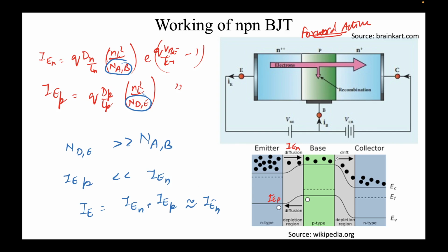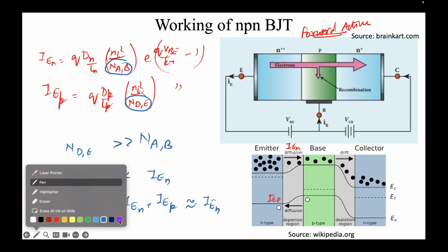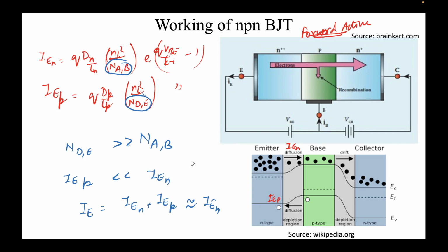And in all this analysis, what we had ignored, I should bring it up now. See, this is a reverse bias junction, base collector, right? If you recall, if a PN junction is reverse biased, there is a JS, the reverse saturation current, that is flowing. We are ignoring that in this analysis, and that makes sense because the electrons flowing here usually contribute to some milliamps of current.